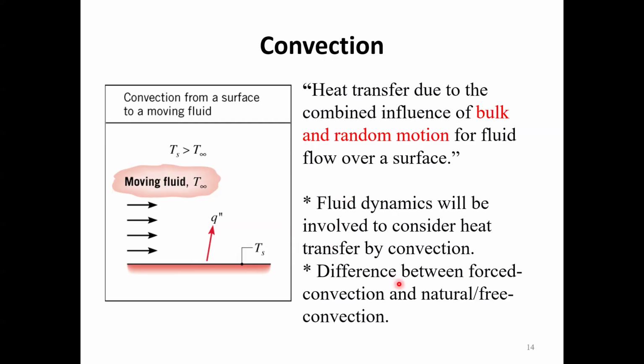And heat transfer by convection can be grouped as either forced convection or natural convection. Say, for example, you're in a room where you're operating a fan, then you are forcing the fluid to move. For example, if you're cooling a cup of coffee with the fan, you are forcing the fluid to move, and it carries energy from the hot coffee to its surroundings, and therefore it cools down. That's forced convection.